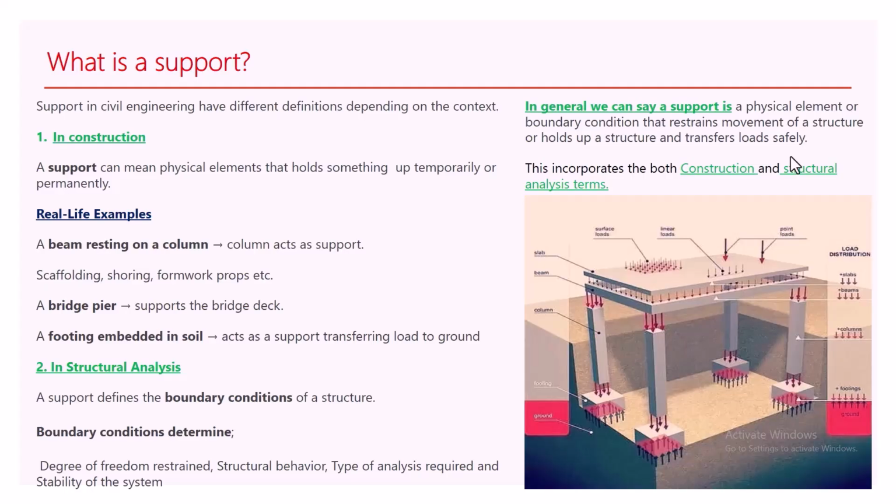As you can see from the picture, the loads from the slab are transferred to the beams, and the beams take it to the column, to your footing, which is the foundation, and then from the foundation to the soil.